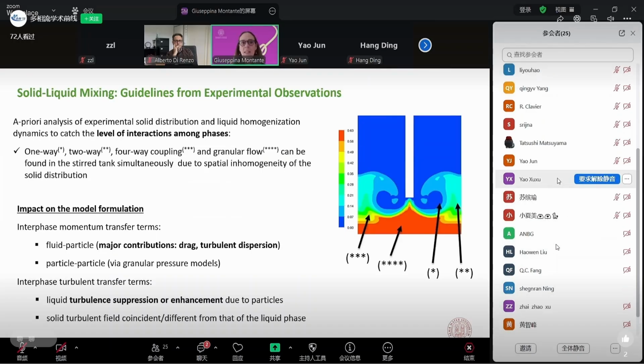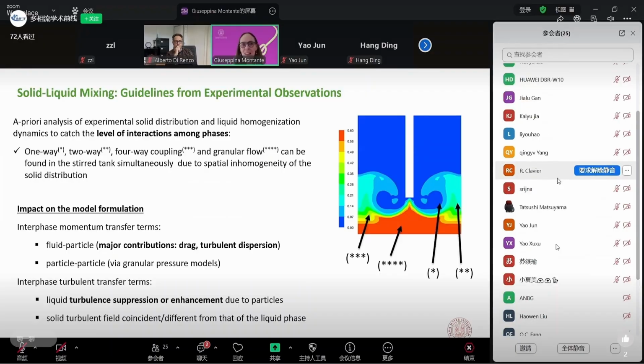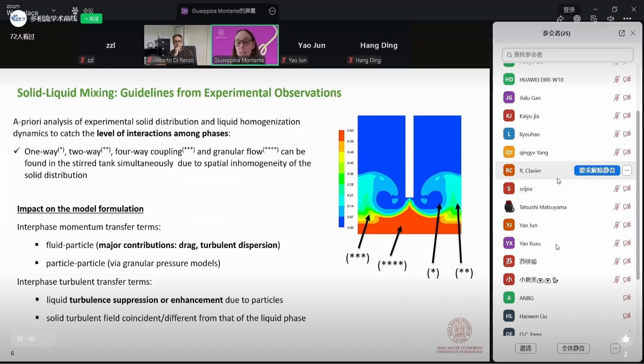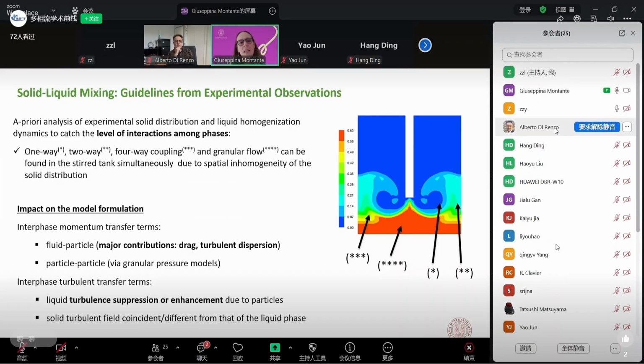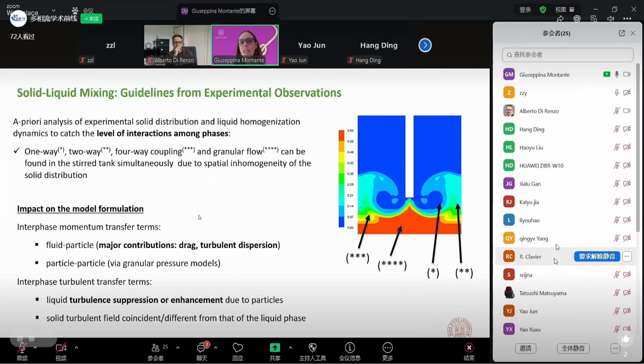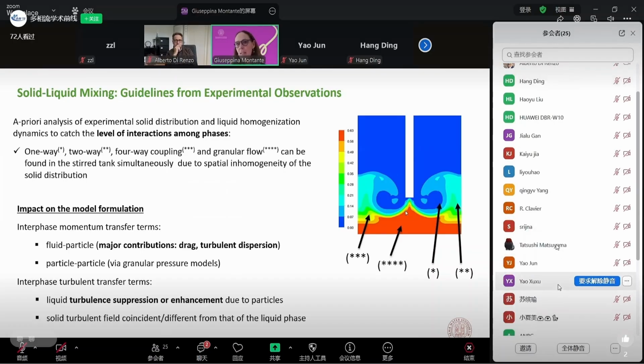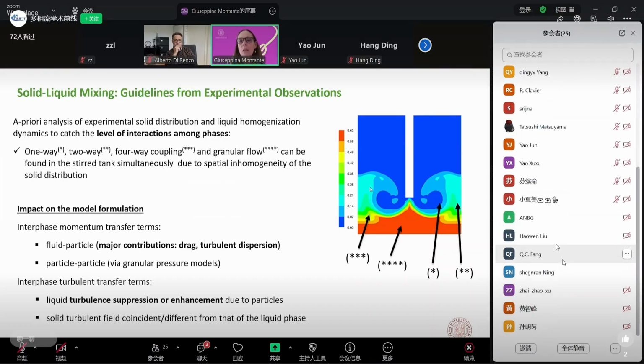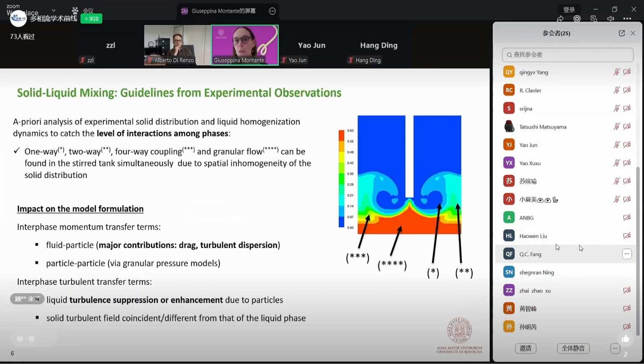Starting from the simplest of the systems that I selected, the solid-liquid systems, we can already see that it is a case of strong complexity in terms of the physics that we have to describe, because in a stirred tank, a stirred reactor or bioreactor, we can have, depending on the solid loading and impeller speed, a very wide distribution variation of the dispersed solid phase.